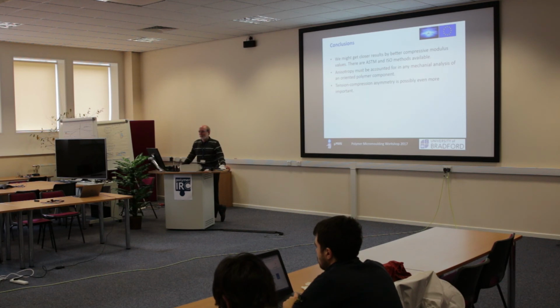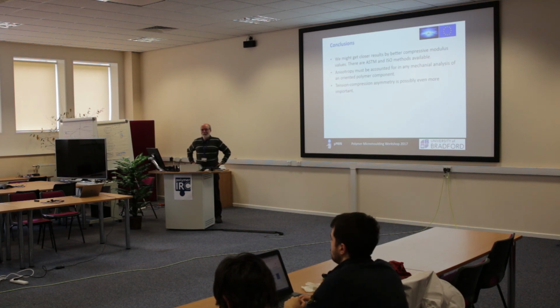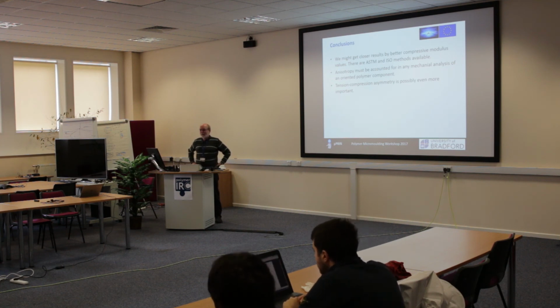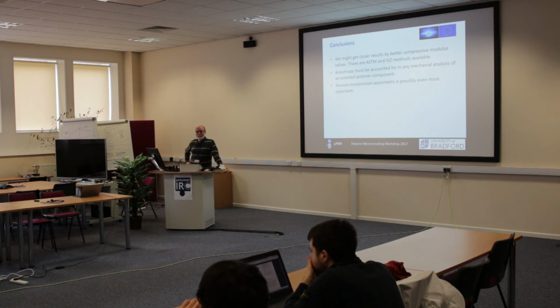So it's not something you can see. You have to do a DSC test, for example, to see that there's a different melt peak, and that indicates the crystal phase has changed. So you have polymorphism, which doesn't really affect your process. It might affect your properties at the end, but this is just at an experimental level that we found out recently, so we don't know exactly what that means.